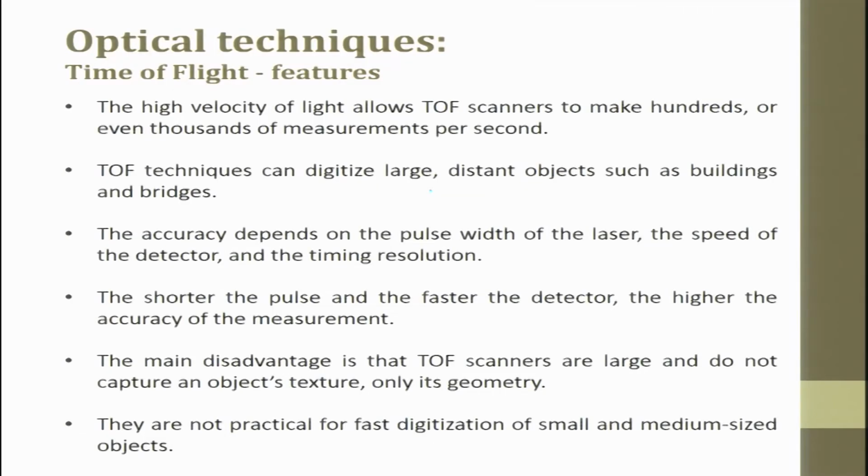Time of flight techniques can digitize large, distant objects such as buildings and bridges. So, if you want to completely scan the Taj Mahal and do reverse engineering, we use the time of flight technique. The accuracy depends upon the pulse width of the laser, the speed of the detector and the timing resolution. So, pulse width, speed and timing are very important.